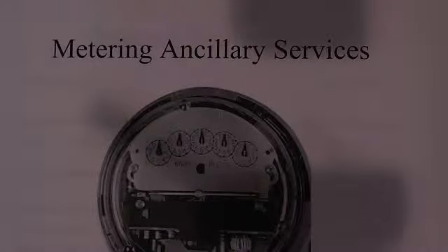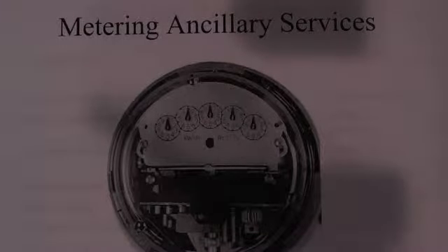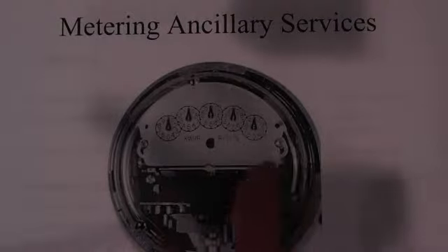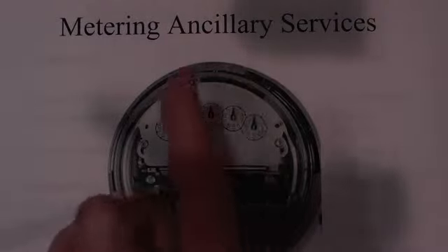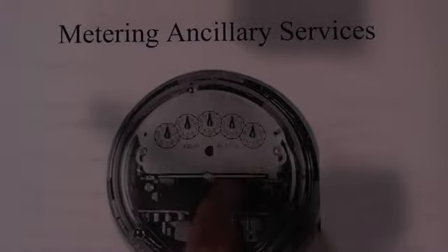Metering is another interesting ancillary service. Somebody has to meter what the loads are consuming. Usually, if I'm a private company and I own a distribution system, then I buy bulk power off the transmission system. But who does the metering? Who owns that meter? Now, this is an old-fashioned watt-hour meter. This is a disc right here that rotates around very, very slowly. It goes around, and as it goes around, these counters up here move, telling you how many megawatt hours.